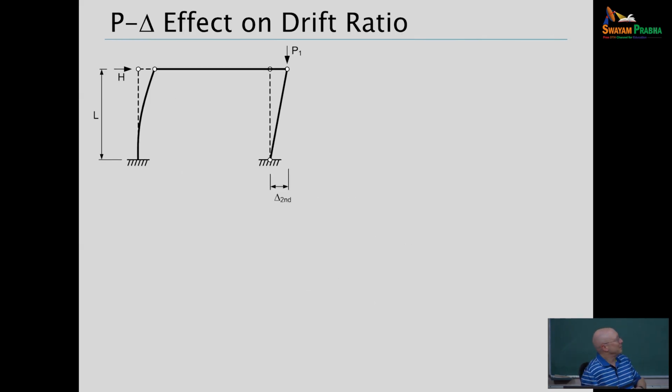So now let's get a little more fancy. Now we've got a cantilever with some other parts of a structure that are tied to it at the top of the cantilever. It's just a pendant strut that's tying it to a column over on the right. Column over on the right is what we would call a leaning column because it's pinned top and bottom. And so if I took away the strut, what would happen to the column on the right? It has no stability. It would just fall over, right? So that means it's leaning on the lateral load resisting system, represented by our cantilever on the left.